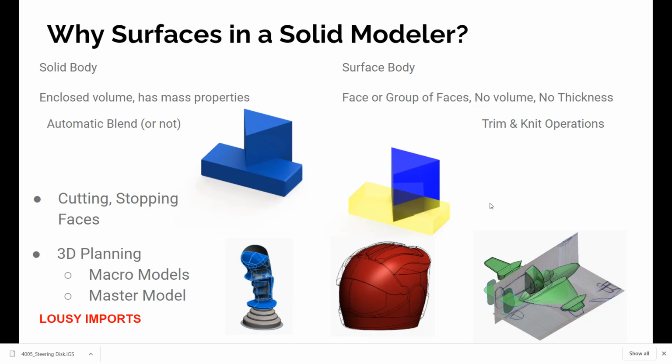One thing is surfaces are very easy to keep separated from each other. When you're doing solids, it always wants to blend into one another. If you have one solid go through another, unless you tell it not to, it'll turn that into a single volume. Surfacing is different. It wants to keep itself as its own solitary item, and then you can use it for keep out areas or a battery box or something like that, where you say, hey, in this area we're going to do this, and no matter what people are extruding around it, it's going to stay independent.